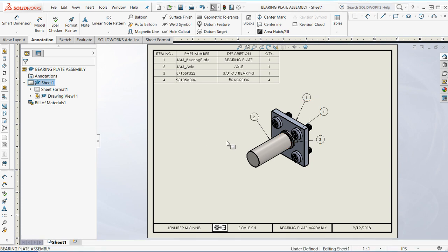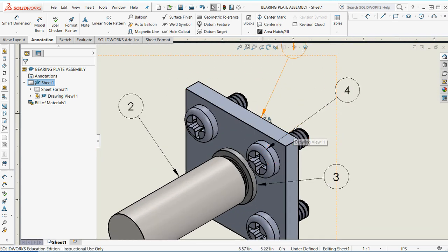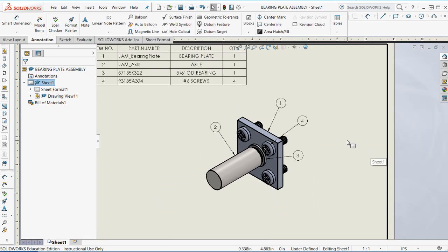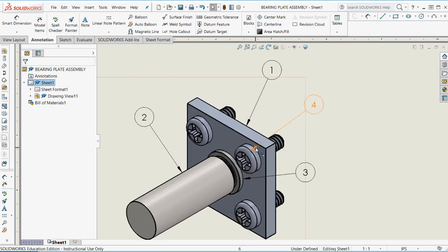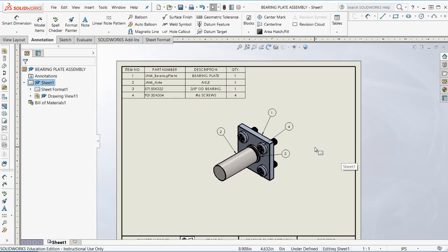And what you can see here is the basic expectation for an assembly drawing, that is, an assembly in a visually useful orientation and parts labeled with a simple bill of materials or BOM. The numbers in this column correspond to the numbers in the balloons. Each of the balloons has an arrow that points to the edge of the part that is being referenced, and they are laid out so that it's very clear what parts are being referenced.